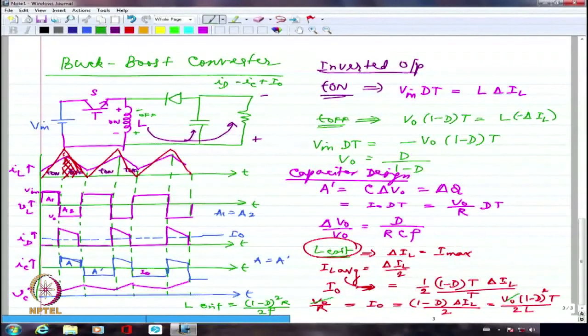So the buck boost converter specifically finds applications wherever we look at a huge range of variation of voltage in the DC supply, which has to be converted finally into a particular constant value at the output for whatever reason. Maybe even for a battery charging application. Battery charging generally is done with the help of a rectifier most of the time. But there are applications where it may be done from solar PV. So the voltage, because it may vary in a large range because of the temperature, you might require a buck boost converter in those cases to bring it back to whatever value is acceptable by the battery ultimately. So these are very commonly used in solar PV applications.